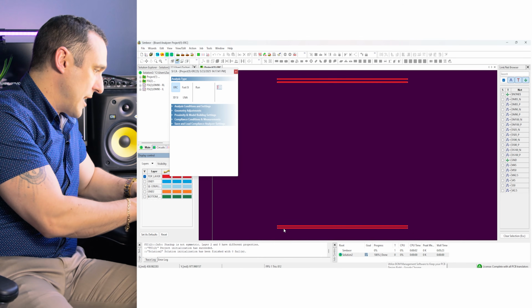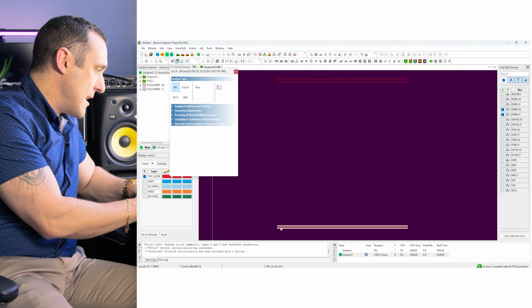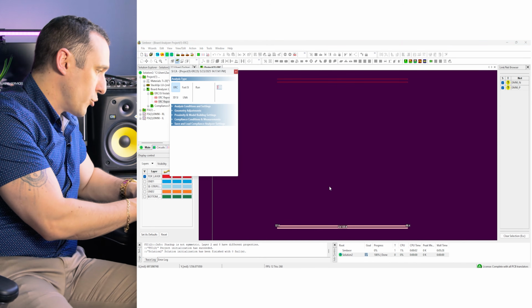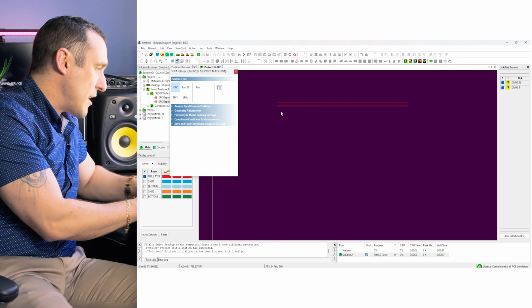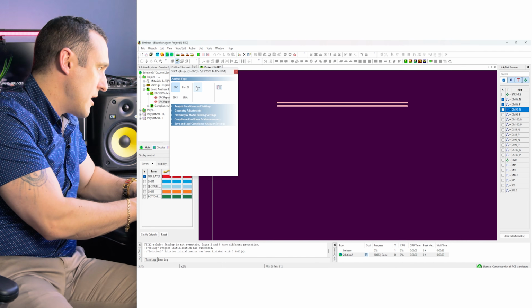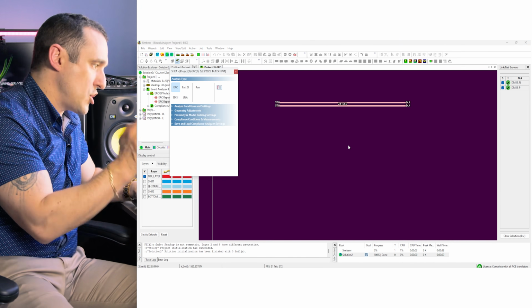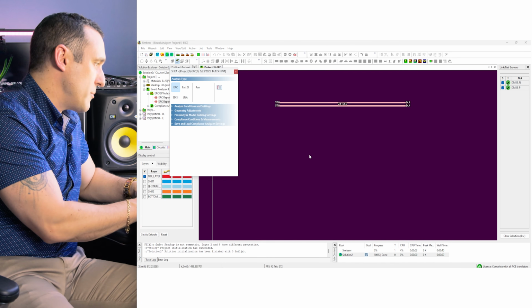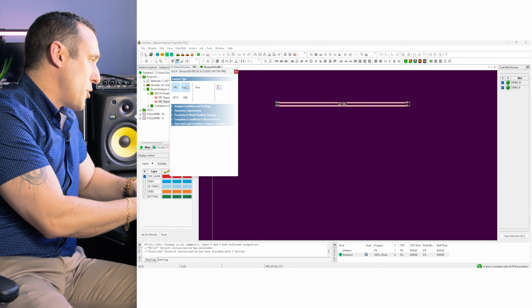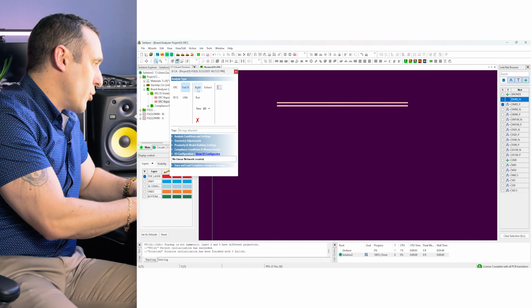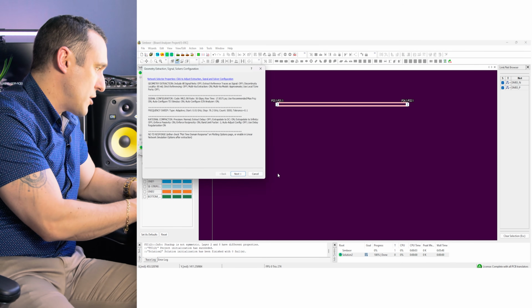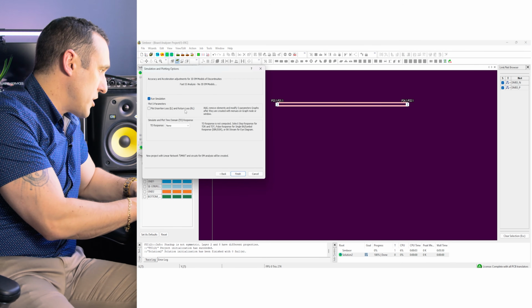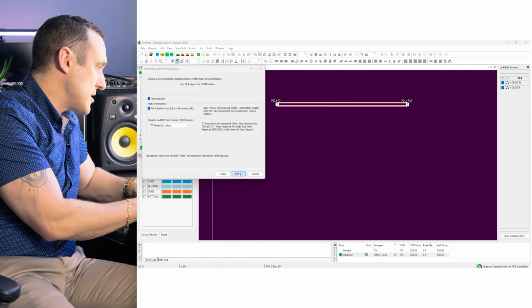First, I can just select one of these interconnects and I can do a quick electrical rule check, and you can kind of see what is the differential impedance for each of these. You can see here if I just hit escape, I select this one, I can do the same thing. I can get a quick check of what is the differential impedance for each of these. So you can see that they're pretty consistent. If I then run a signal integrity simulation just based on the cross section, we can just click through the wizard here to get some quick results.